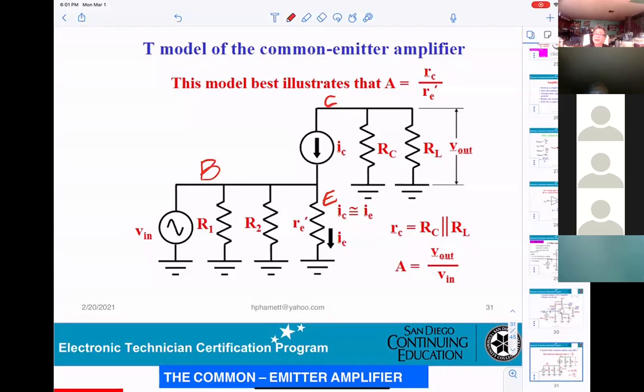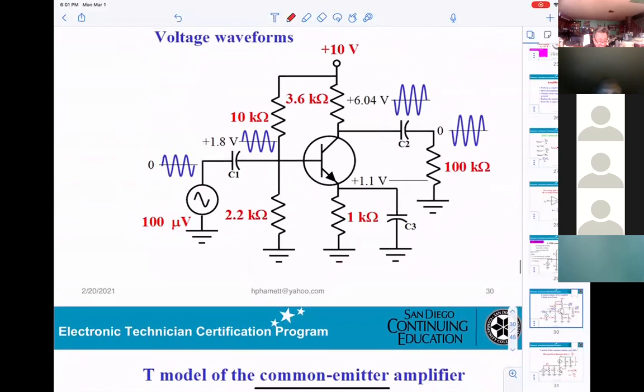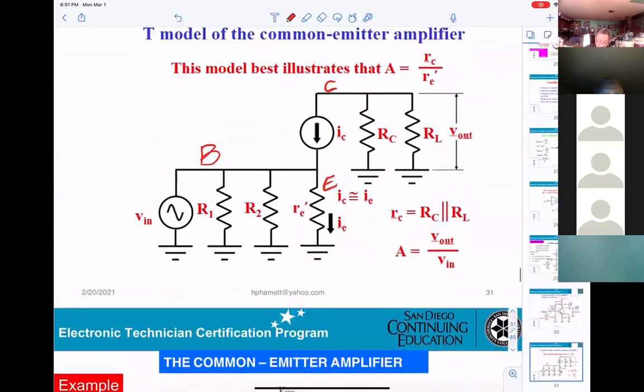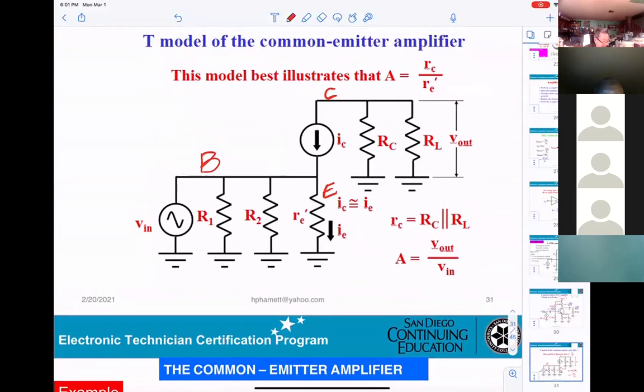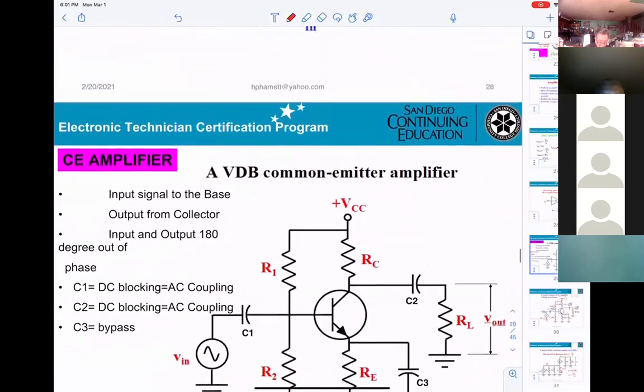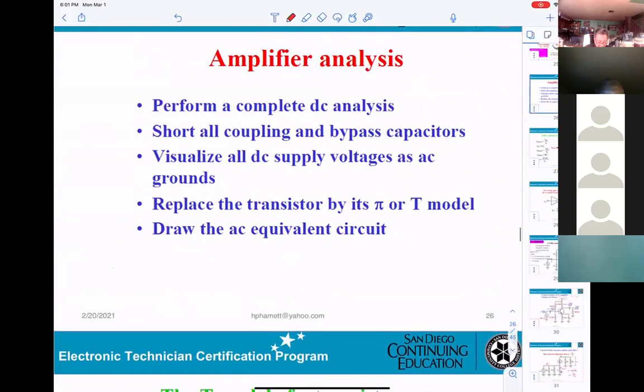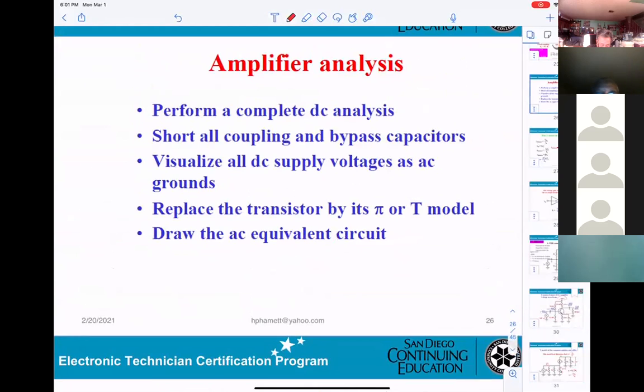My question is, if you're looking at the DC, you get VCC right here. However, when we go to the AC model, you didn't see that 10 volt. Where did that go? Shorted, isn't it? Yeah. Go back here. Okay. Right here. Grounded. The DC source must be grounded.